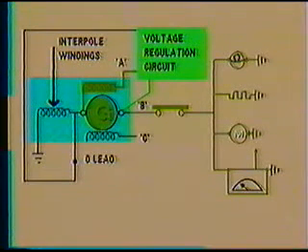The C terminal is where power is connected for using the starter portion of the starter generator. This connection leads to a separate set of windings that are used to make the generator into a motor to drive the engine during start. This circuit is of relative unimportance to the generator circuit, although, as we will explain later, the starter windings within the generator do play a part in the generator circuit as well.